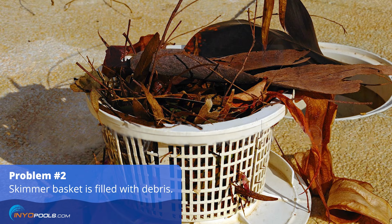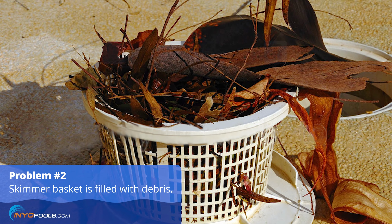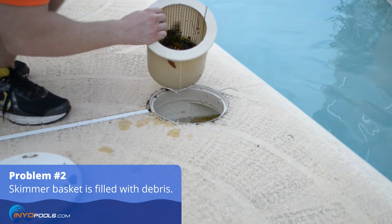Next, take a look at your skimmer basket. If your skimmer basket is full of debris, you're effectively shutting off the pipe between the skimmer and the pump, resulting in low flow. To fix this, simply clean and remove all the debris from the basket.